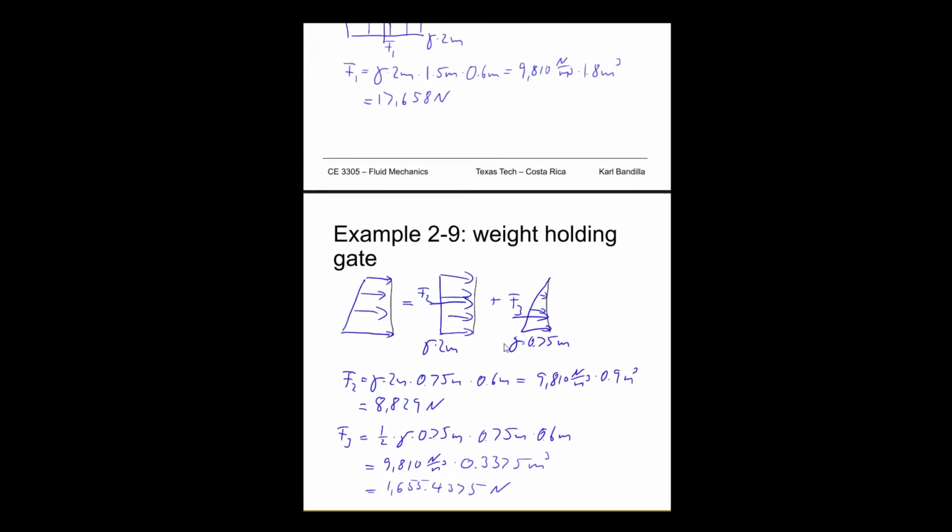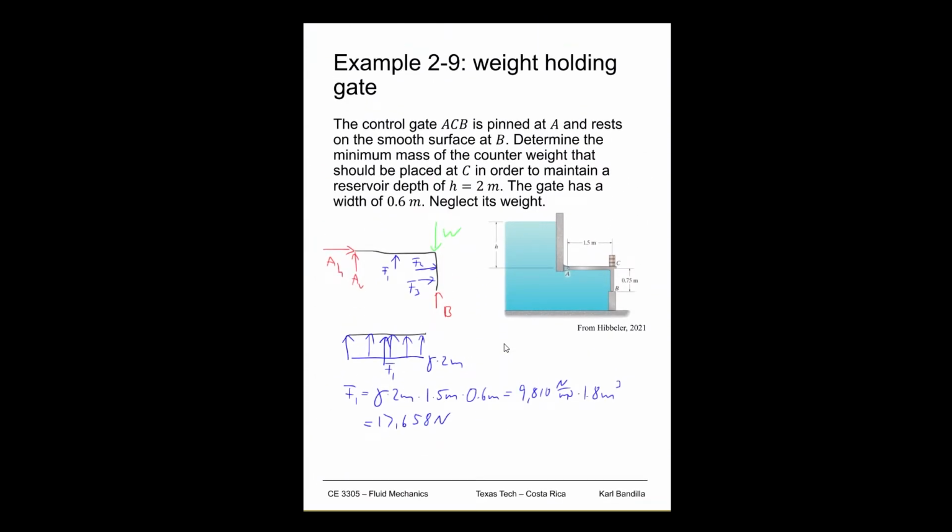So if we go back to our free body diagram up here, that means the only unknowns that we're left with now are all the reaction forces and our weight, because we're not given the weight. Now, if you look at this, you might get a little concerned. How many unknowns do we have? 1, 2, 3, 4, because we don't know what the weight is. How many equations can we get? Well, we can maximum get 3 equations out of our free body diagram here. So we have to think a little bit before we start acting.